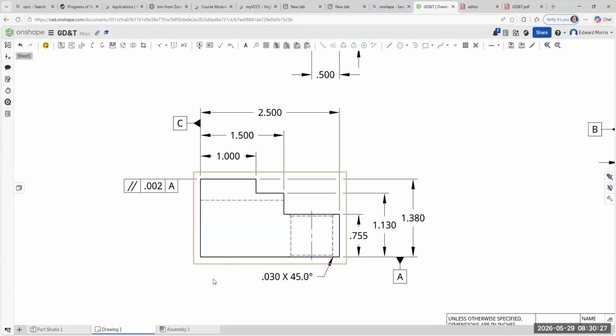And the way you would check it is you would put this on a surface plate, which is a precision measuring or precision surface, right? You would place this on, then you would get a dial indicator and you would run it across here and see how much off. If you're less than 0.002 as you run your dial indicator across here, you're good. But if you exceed that, then you got a problem, right? All right, so that's the first one.